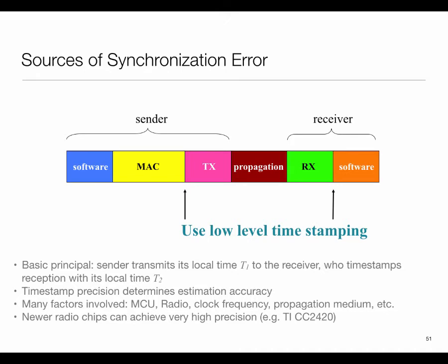What used to be done early on was timestamping out here. This is how NTP works: the timestamp is taken somewhere out in the stack. But ideally, particularly with the kind of platforms you have in embedded systems, you can afford to timestamp at the lower levels. You can timestamp here and here. Timestamping further out is very hard because that is on the other side of the RF circuitry. So this is where timestamping could usually happen.